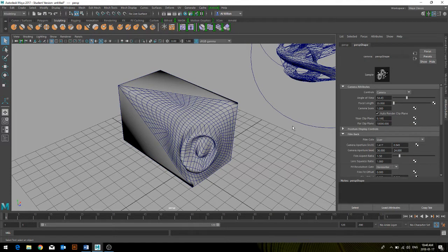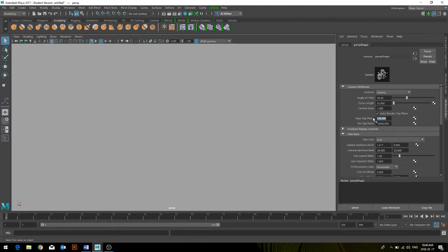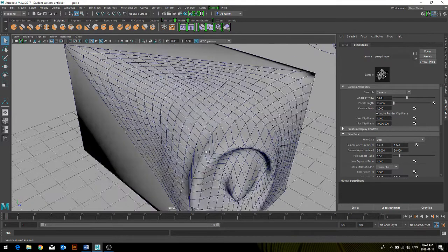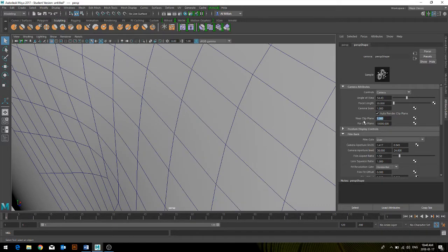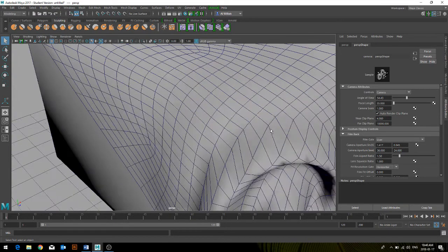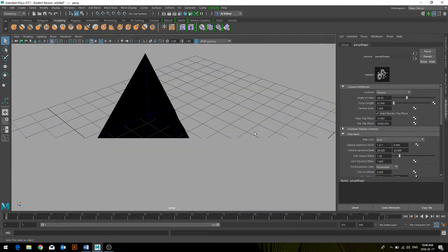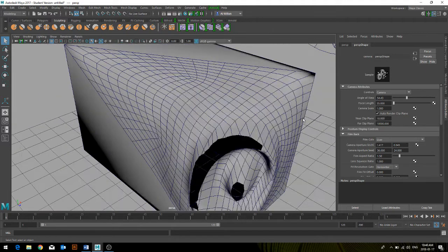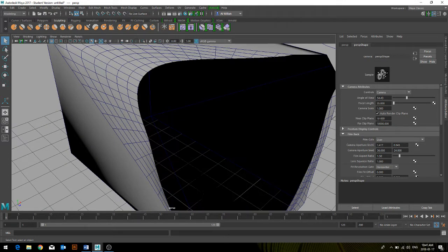I'm just selecting my near clipping, and I'm trying to, if it works, I'll give it a different number, like 100. That's too much. Maybe 10. And you can see it's 1. I should make it like 4. Okay, now you can see if it's actually 15, it's too much. If it's 10, okay, now you can see as I get close to my object, it's clean, it's deleting. So some parts at the front I can't see, but instead I can see the inside of my geometry. So that's the 10 distance from my camera point to the object, it's cutting off.